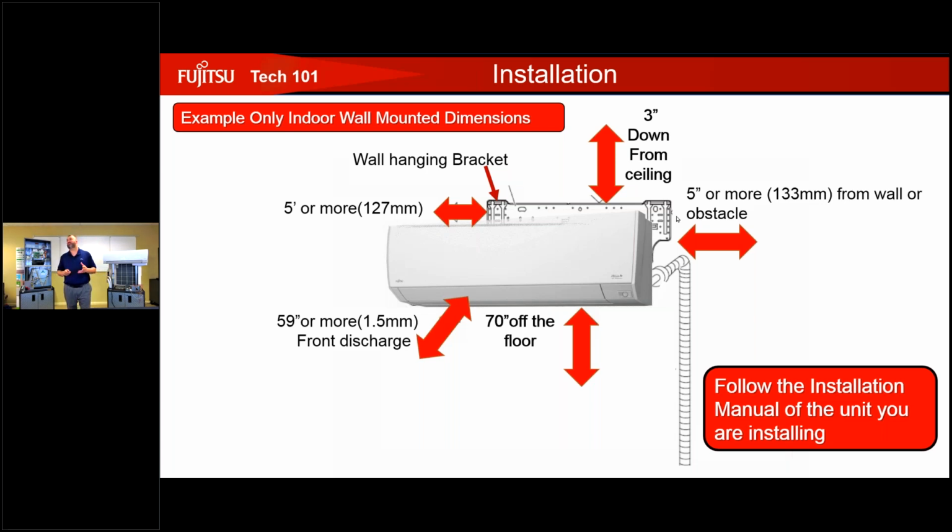So I would always recommend maybe a little bit more. 5 inches is basically a screwdriver length. You're not going to be able to get your head and your hand in between that 5 inches. So maybe more closer to 10 to 12 inches off the wall, just so you can see what you're actually trying to troubleshoot on that indoor board.